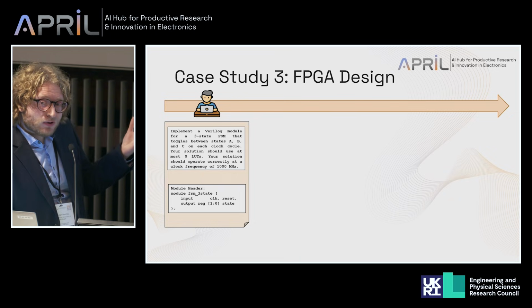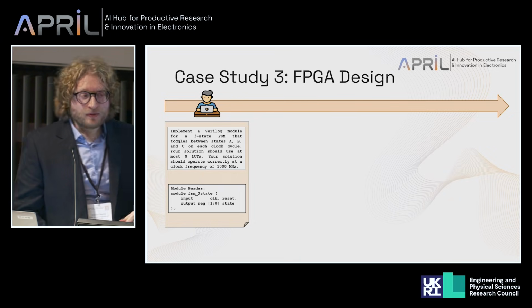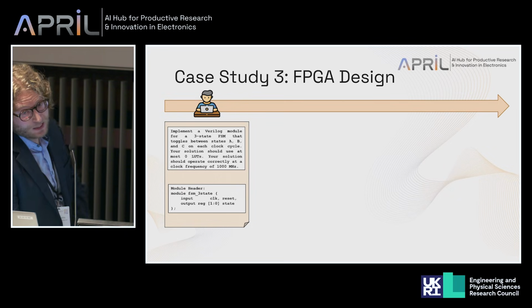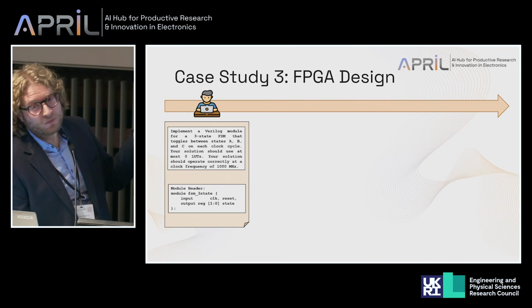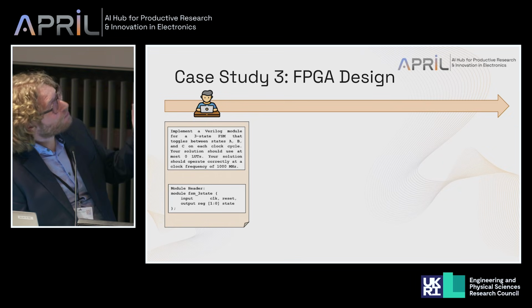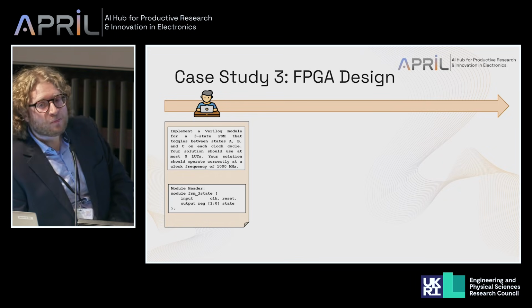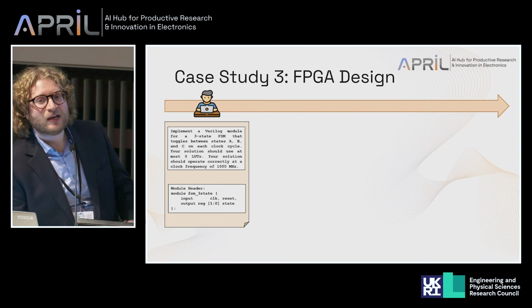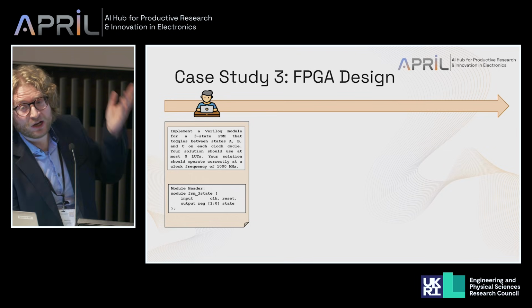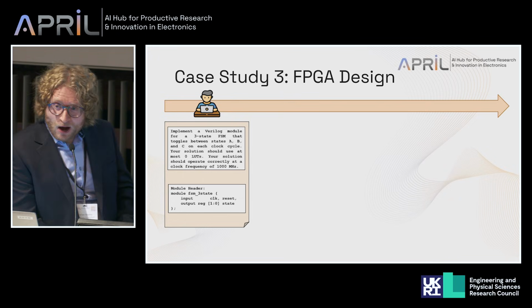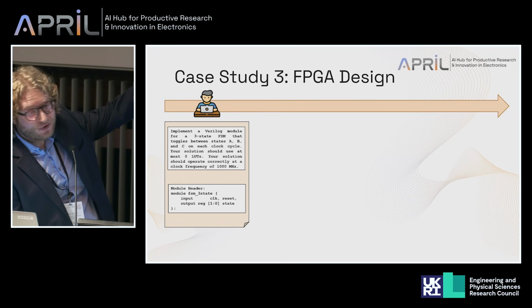Now, in the case of FPGA design, the procedure is quite different from what Panayota and Pratibha have explained. In particular, in our input prompt, we start from a specification of the circuit that we would like to achieve, as an example a finite state machine, but also some specification about hardware constraints. As an example, we would like to use a given number of logic resources, lookup tables (LUTs), and also a given target clock frequency. Other than this information, we provide the input and output ports of our digital circuit that are defined in the bottom pane.